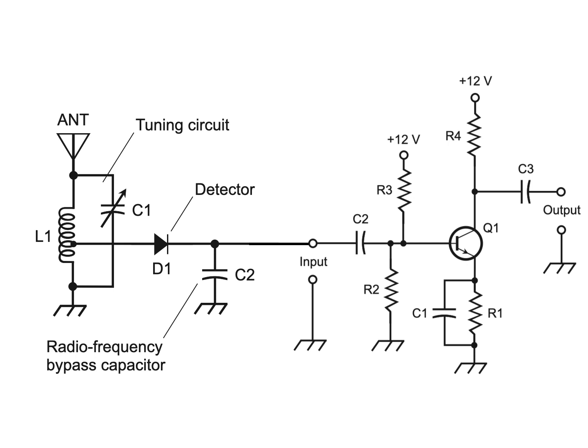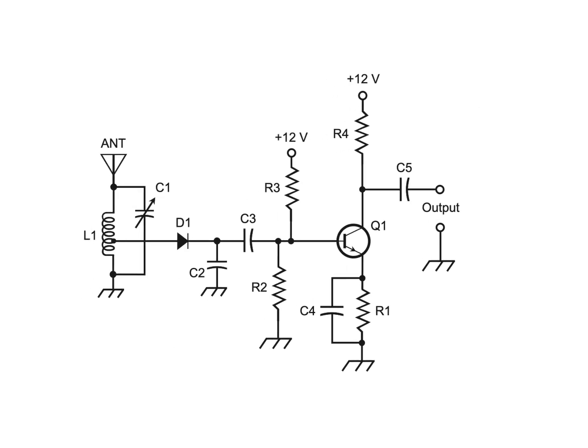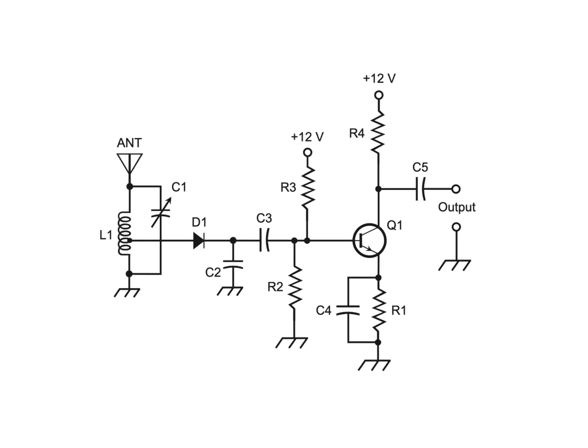of the preamplifier. This circuit diagram looks at first glance more complicated than each of the previous two diagrams. But is it really? If you look at this diagram for a minute or two, you'll notice that it's nothing more than the composite of the crystal radio and the audio preamplifier that we've just seen. The components are renumbered, generally going from left to right, the direction of signal flow through the system. You never want to duplicate a component designator in any schematic. The connection between the original crystal radio and the preamplifier corresponds to the short, connecting line that goes from C2 to the left-hand side of C3.